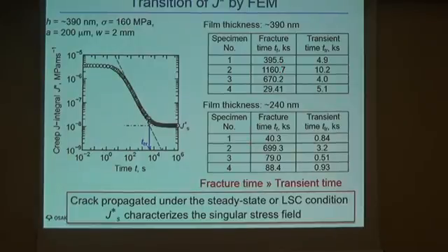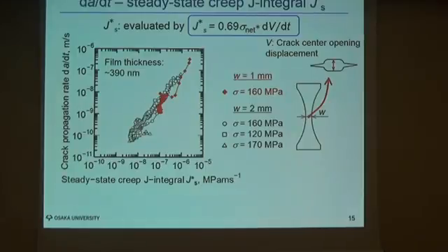So this suggested that in these experiments, in almost the entire crack propagation stage, the crack propagated under the steady-state or large-scale creep condition. In that case, J*_S characterizes the singular stress field. So we evaluated the relationship between da/dt and the steady-state creep J integral J*_S. Here, the J*_S values were evaluated by a simple approximate equation.